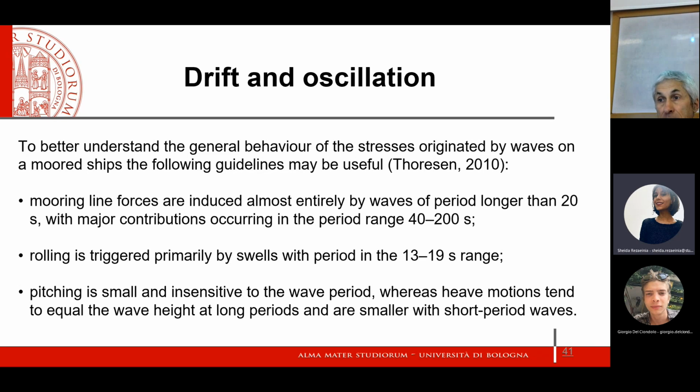Rolling is triggered primarily by swells with a period in a shorter range. Pitching is small and insensitive to the wave period, whereas heave motions tend to equal the wave height at long periods and are smaller with short period waves.